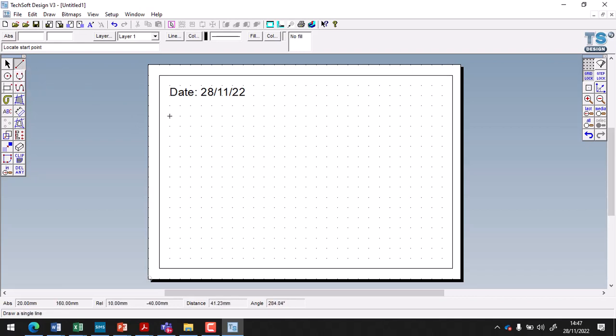So I'm going to place the lines. I'm going to draw lines at 50 millimeters. So if I click on there, I could go 1, 2, 3, 4, 5. Now that's 50 millimeters. That's one way of doing it. I could click and then press the arrow keys, 5, and press enter. That's another way of doing it. Or I could press on here and then look at this area here. If you look there when you're moving your cursor, now I know that's 50. Okay, so that's 3 ways of drawing a line.